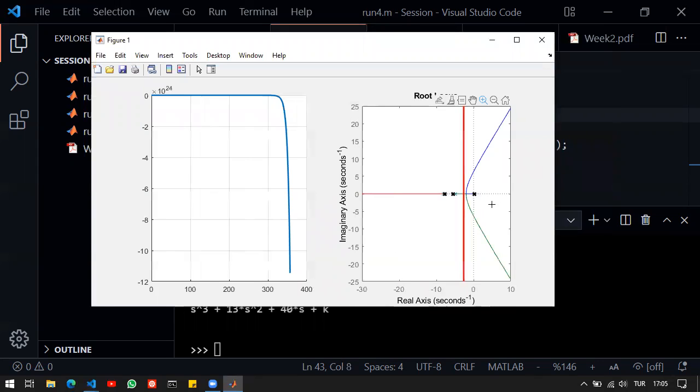Therefore, using a p-type controller, I cannot design a p-type controller that ends up in settling time 1.5 because I'm not on the root locus plot. So this shows me that for this system especially, I have a natural settling time limit because lower settling times mean faster response, but the system cannot perform at that speed.